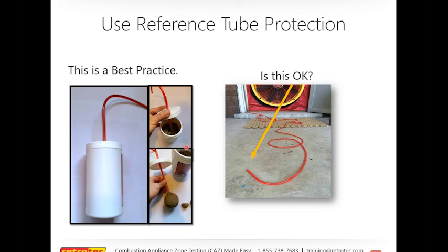And then the idea, again coming from Pete Kutcher here at CETA Weatherization, he said, why don't you just stick this into a box of rocks? This is a very loose top. Then put the top on there, and then you can connect your reference hose, and the reference hose will not be subject to wind-driven or other weather events from the outside. So here we're being fastidious about making sure that our differential pressure is right.